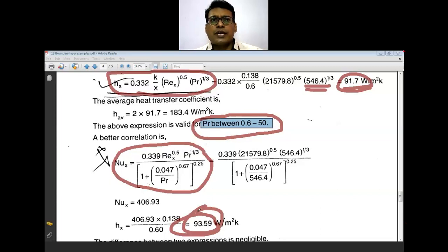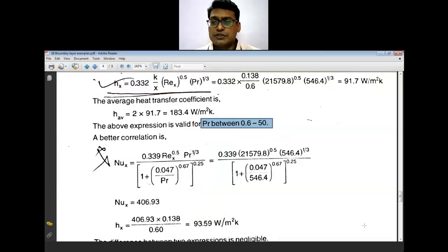But with the progress of time, that pipe may corrode and form additional resistances. Some deposits may be there on the pipe. So again, that is your fouling resistance that will be there. Both things are going to affect your heat transfer coefficient. So with the progress of time, my heat transfer coefficient may decrease. So it is a function of time as well as depending on the different variables.